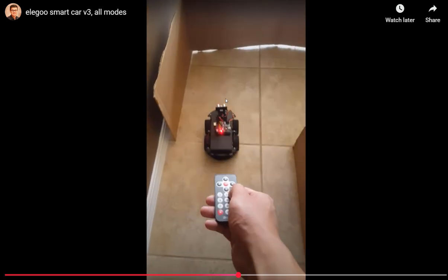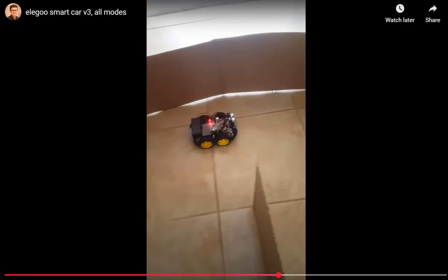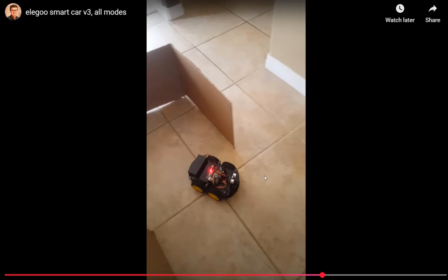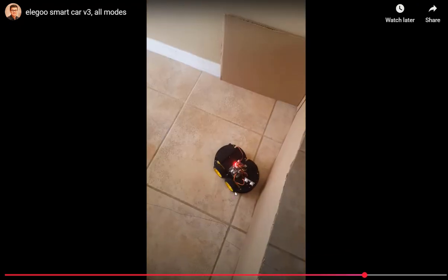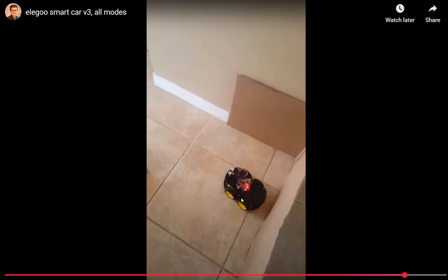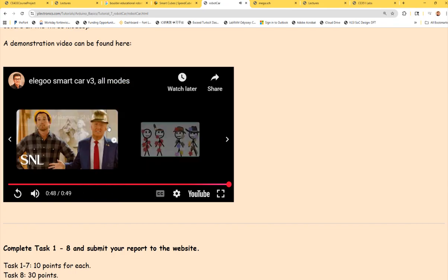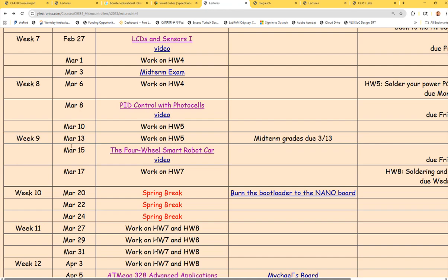And also, this is a distance sensor, the ultrasonic sensor. It measures distance. Whenever it sees an obstacle within a certain distance or range, it will stop, measure the surroundings and find a way out of the maze. It's not super intelligent because it's a really simple loop, but it does the job. The success rate is probably not 100% because it's not AI based. It's really simple. You could also do that. The robot is available. You can modify it, or design your own board to interface with that robot if you want.